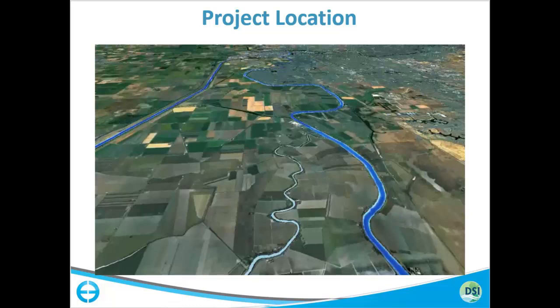And you can also change, for example, this is just the water level here. So if you want to see sediment distribution or whatever parameter you are interested in, you can change this. When you are exporting from EE, you can specify what parameter you want to visualize in Google Earth. Then that's how your color contours will change, and you can display those.